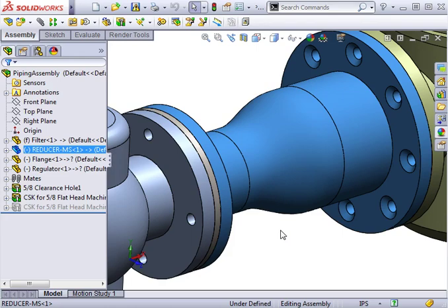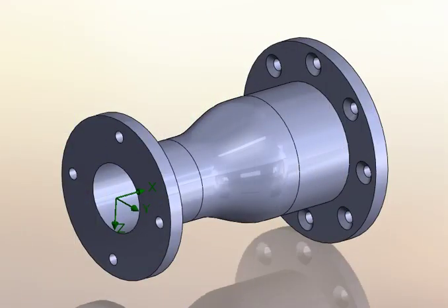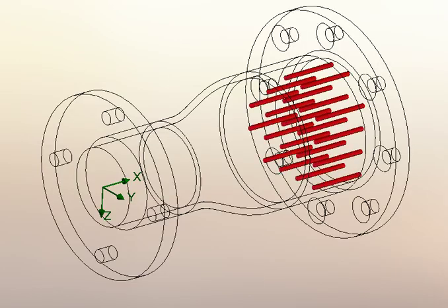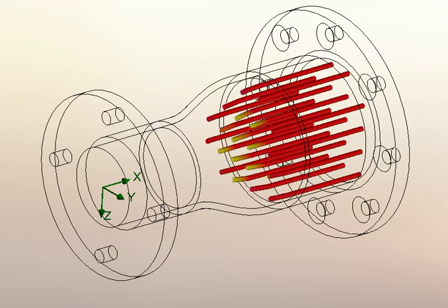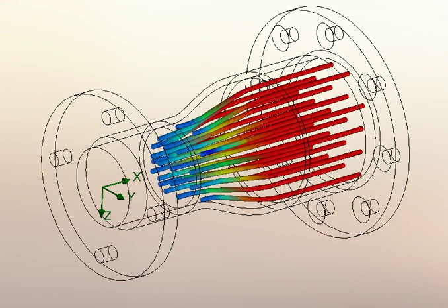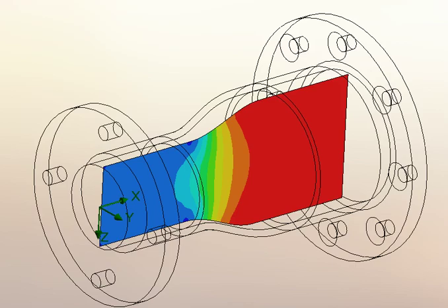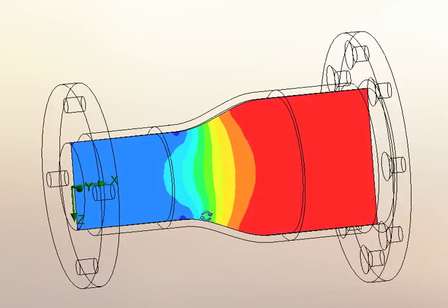Well, one way to find this out is by using the full version of SolidWorks Flow Simulation. With a simple study that accounts for the inlet, outlet, flow rate, and the type of material flowing through it, we're able to quickly find out how much pressure the reducer will experience. For this exercise, we'll be using a pressure of 1500 psi.